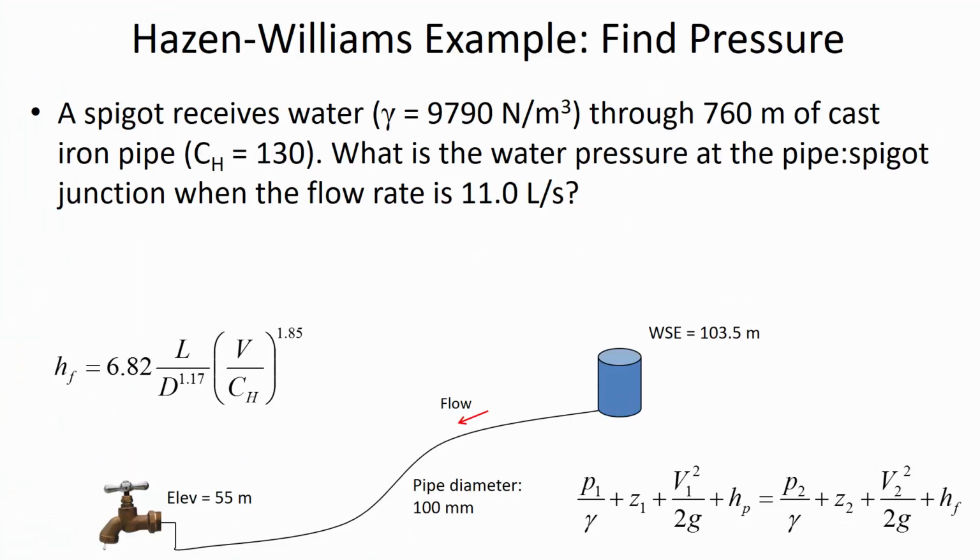That means that not all of the energy was being used to overcome pipe friction. Some of the energy was being left in reserve so that there would be pressure in the pipe. If you exchange that energy, instead of keeping some of it in reserve to pressurize the pipe, and you spend it all on overcoming pipe friction, then you can move the water at a faster flow rate. Remember that this was potential energy. The water in a tank up on a hill is potential energy, and we're transforming it into movement, which causes pipe friction and then pressure.